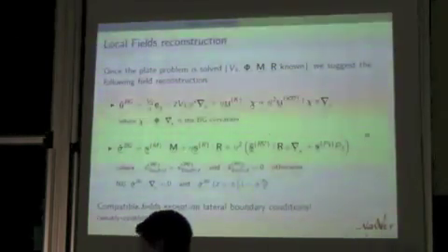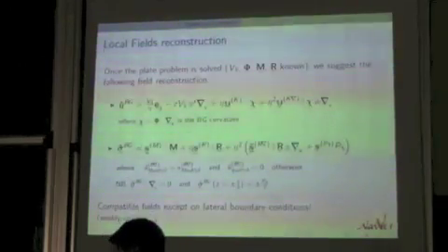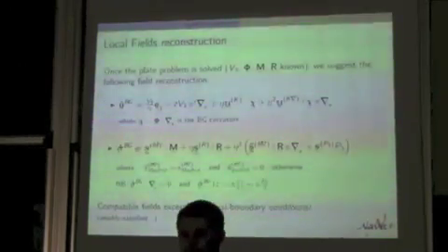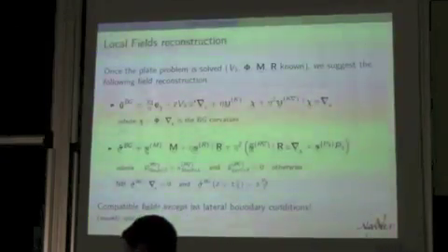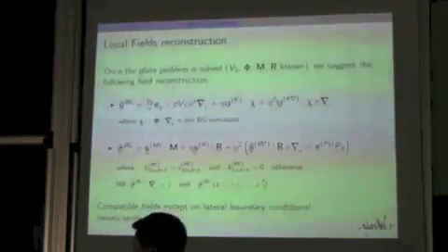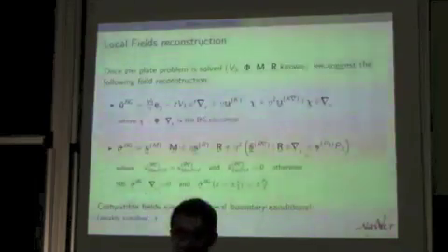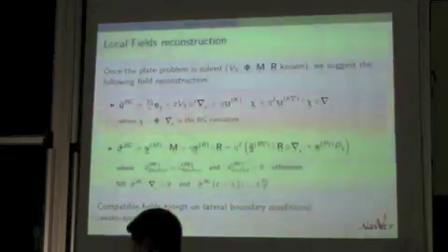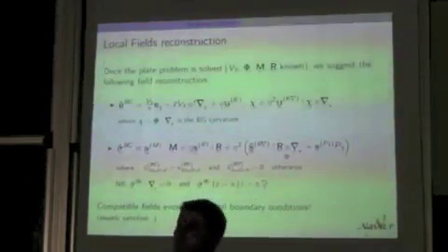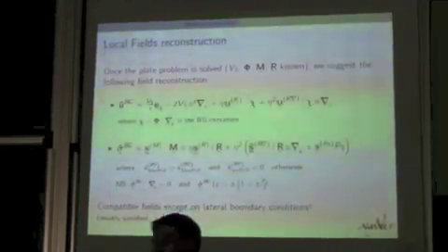Okay. So this is for the displacement field, and I can build also a stress which is compatible. Okay, so I need the first two terms I've used to define the bending gradient theory, and I need to add some pieces of the next order inside the definition of the stress. And if I do that, I manage to have a stress field which is 3D compatible.